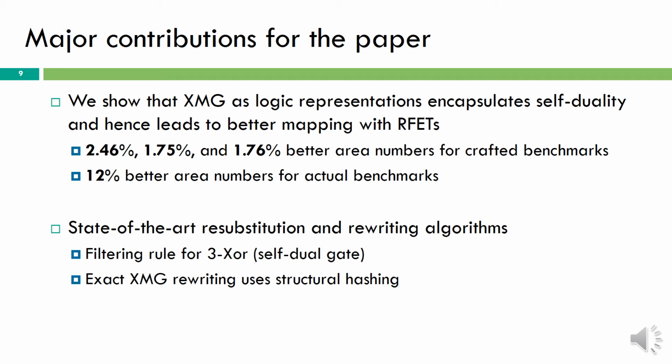The other two important things are that we propose two interesting algorithms: the resubstitution algorithm and the rewriting algorithm for XMGs. We also propose a filtering rule for 3-input XOR. Let's try to look into these in more detail.